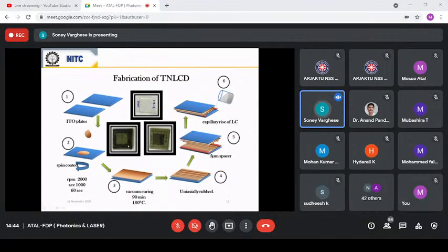But in the middle, you can see that since there is a twist in the liquid crystal molecules, light is coming out. Right. So when you apply electric field, you can see that just the opposite takes place. So the middle part, you can see that the light is blocked. The twist is lost, so light cannot come out. So this is a typical display, a small display device we can make.